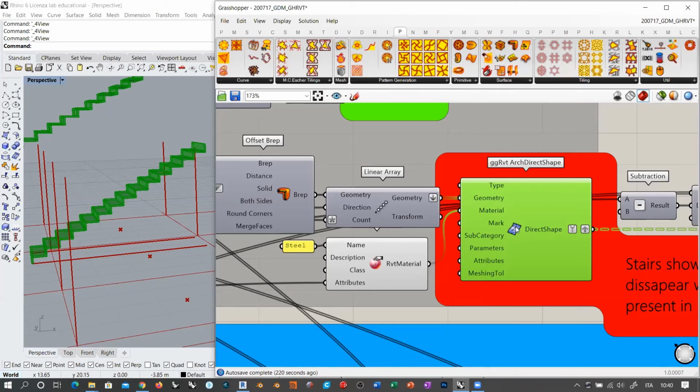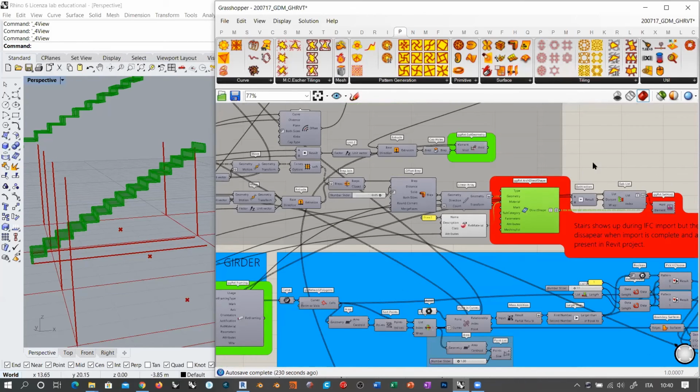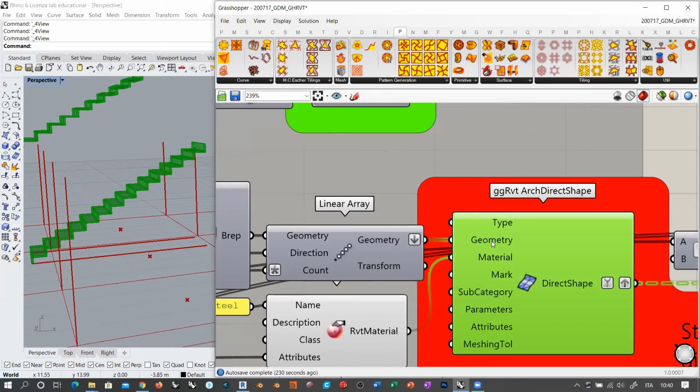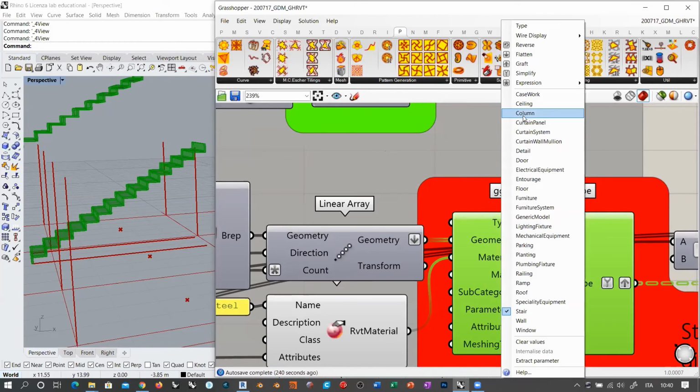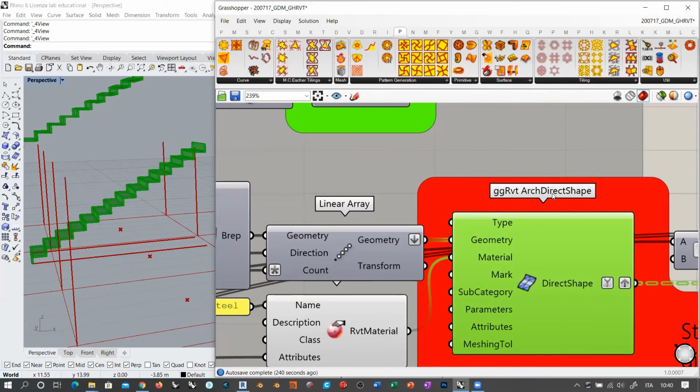So if you want to create an architectural column, you could also define the shape of the column, not only the axis, because you cannot use the axis only like we did with columns. You must define the 3D column and plug it into the geometry and say that that thing is a column, which is going to be considered only as an architectural element, not a structural element. Okay, so this is the only alternative that we have right now to define an architectural column.